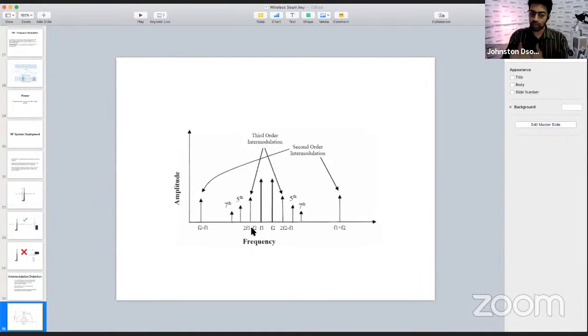Okay. So whenever you're setting up a microphone system, make sure that you follow the grouping system of the manufacturer. And unless very necessary, don't try to make your own frequencies for it. Try and follow the grouping system. So go scan on the receiver, check out which frequencies are free where, and try to make sure all the frequencies are tuned in the same group or same bank.